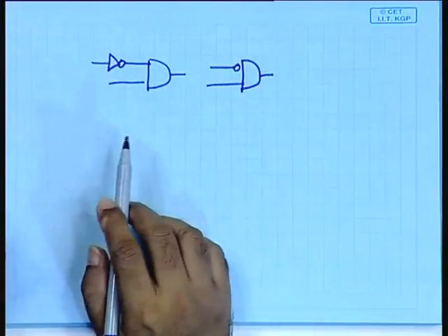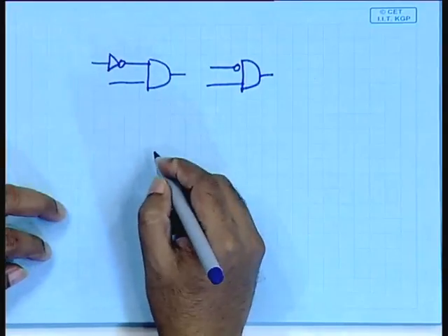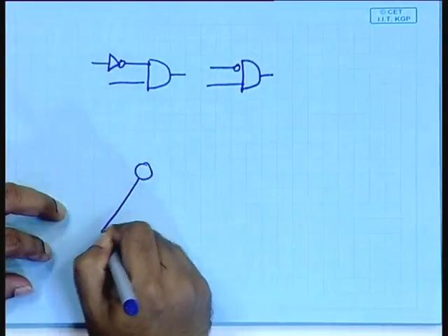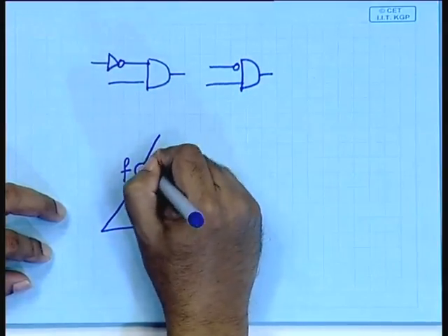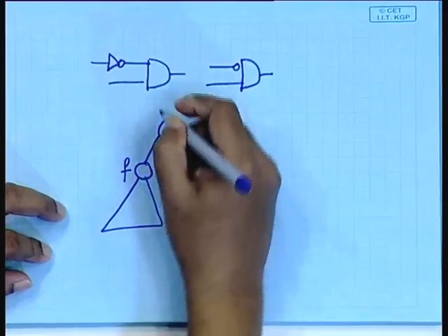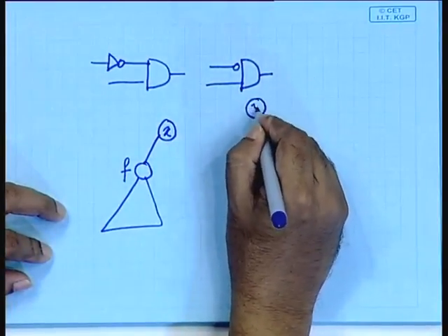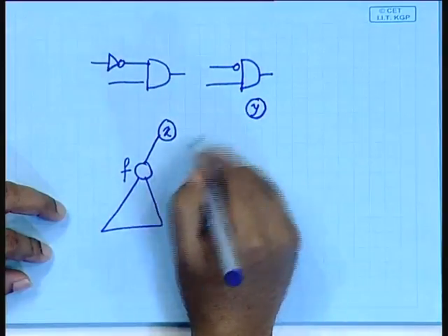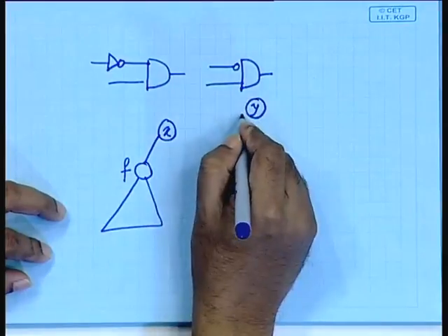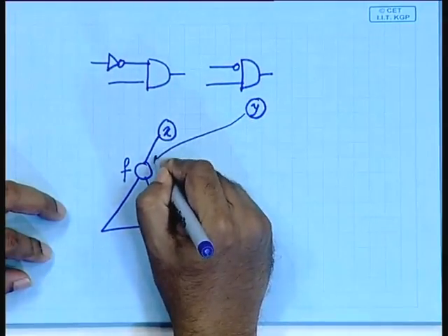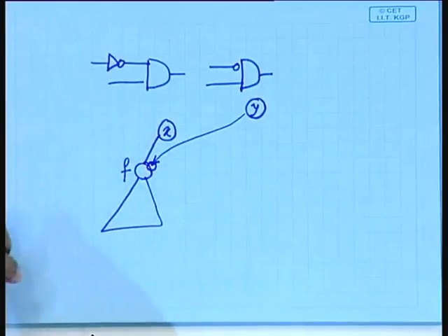So, in the BDD also there is a nice optimization which is done, that if you have the BDD for a function f, right, which is maybe for some variable it is connected to this, and then somewhere in the BDD you need f bar, then instead of creating another BDD for f bar, you can point to this using a negated edge.